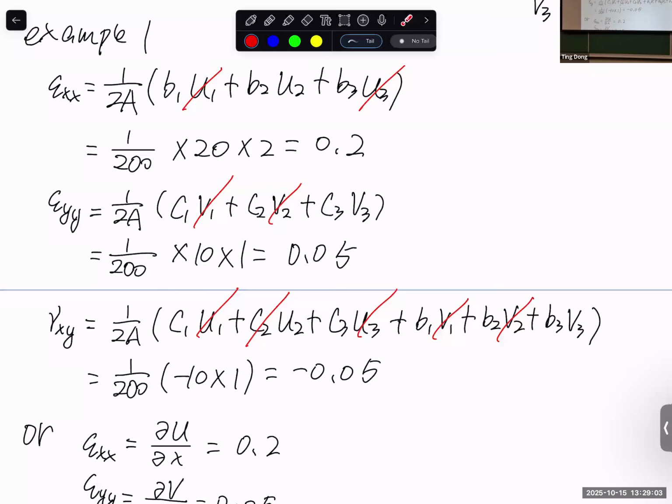And it's not just that the student license, you can only use up to 1,000. I'm using the research license, which is much more advanced than what you use. But even with the research license, if you want perfection in every detail, the model itself cannot be imported into the FEA software. So my job is to make it smooth and remove the details.